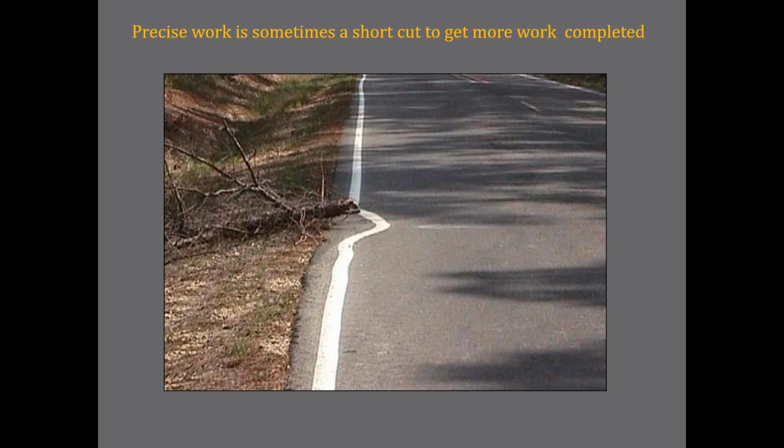But I always say to people, how many things are your maintenance people or maybe your operators doing where they take a little shortcut like this when they're supposed to be doing something precision, and for what reason? Maybe it's time. If we're doing too much reactive work and we don't have a lot of time, maybe our precision work takes this shortcut. If we don't have a written procedure in place, do we take this shortcut? And again, when I talk about precision maintenance, do we need written precision documents for every piece of equipment in our plant on the rebuild? No, but once you do the asset criticality, once you determine what assets are critical, we need to do precision work.